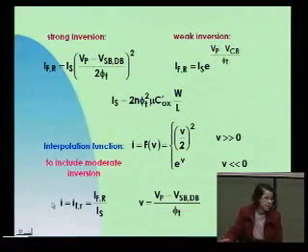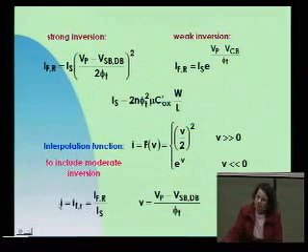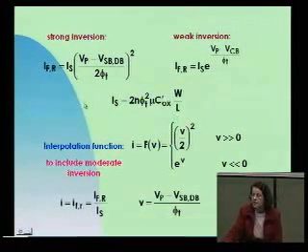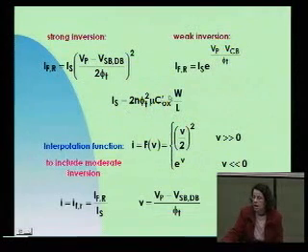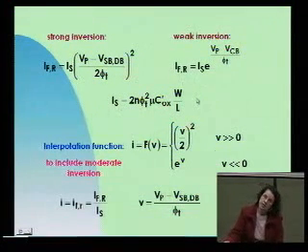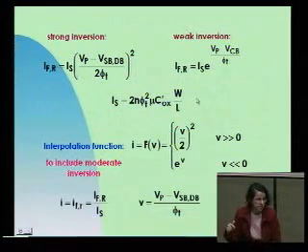I normalize the forward saturation component with respect to this specific current, which takes into account the technological information and the geometrical information of the device. The specific current is used in the EKV model, but also in the ACM model, as we will see soon.